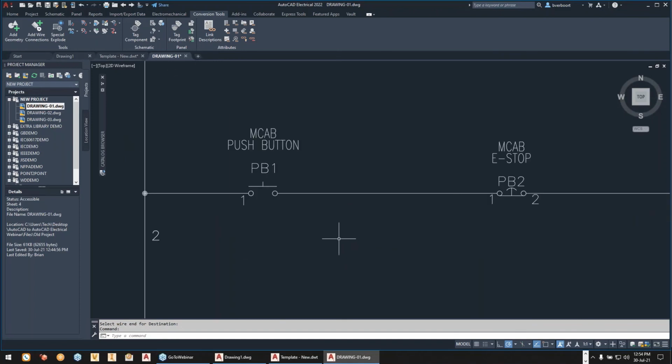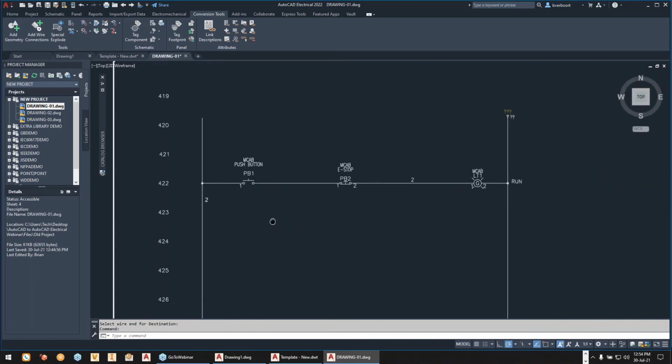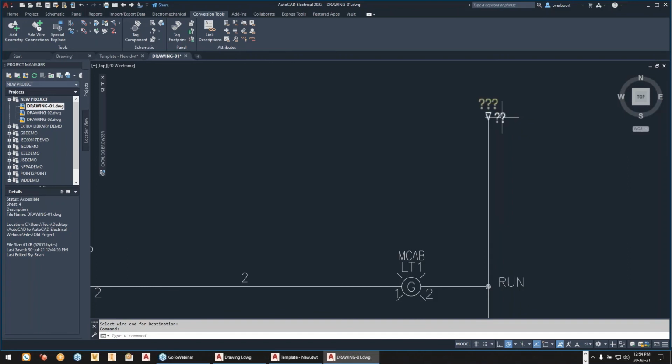So now there's attribute information associated with that block. You see here that it's previewed the potential for a source and destination, but it's unaware of where the connection's been made. So just simply defining the source would then give the cross-referencing in this information automatically. And as I hover over that, you can see it's been added to a layer called SYMS, which is one of the things we can modify, or it's just a default behavior of the software.